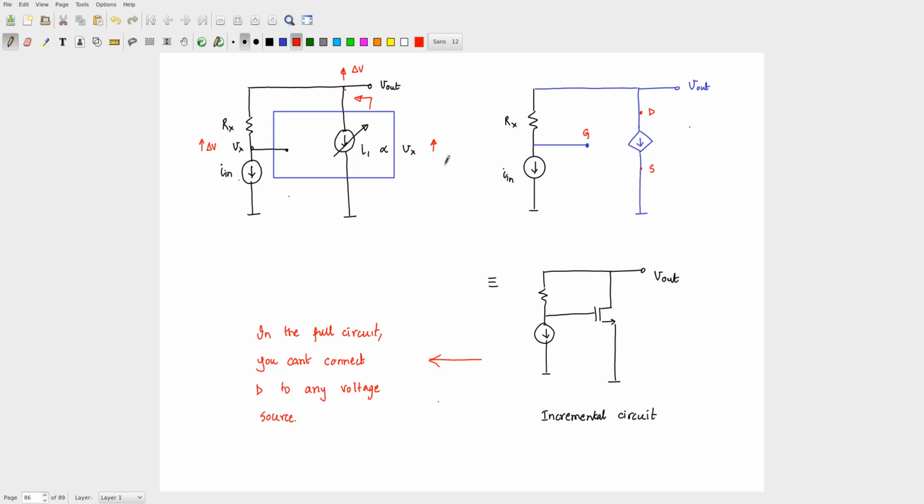If you pump in some current, the voltage change will be 0, right? That's easier. Don't look at it as giving a voltage and then your current going up. That will complicate you. Apply a current so that the voltage goes up by delta V, and the whole feedback loop basically kills the delta V. So your resistance is nothing but delta V by I, and that will be 0. Anyway, that little bit which I mentioned now, you can think about it. It's just to justify that whatever we had makes sense.